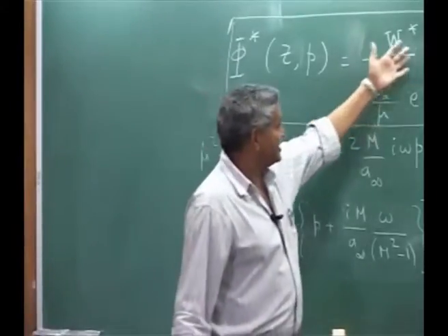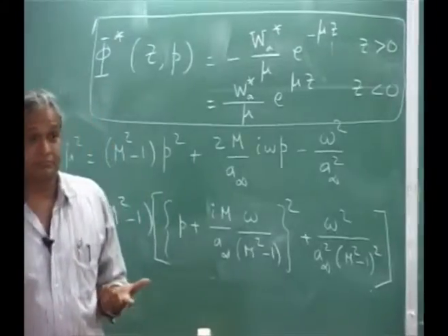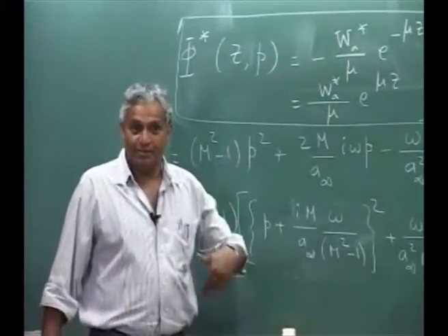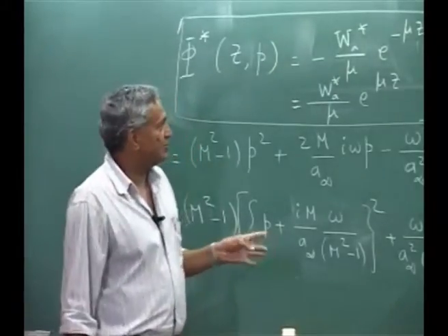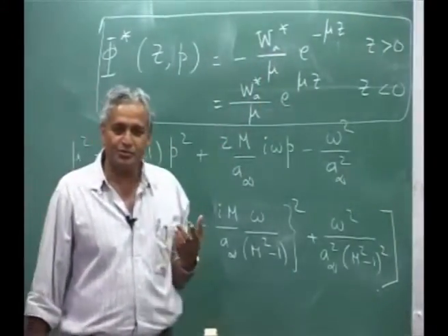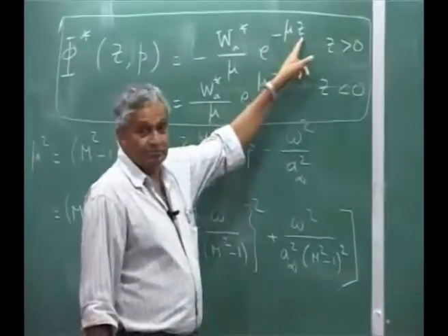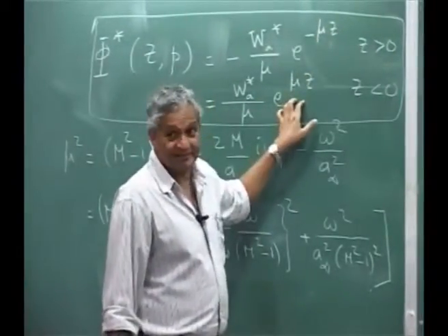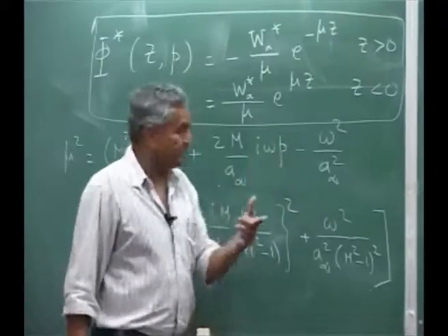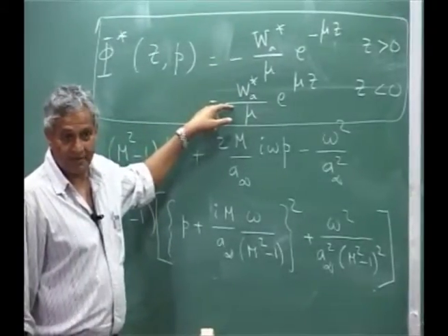Otherwise, you have to get this Laplace inverse of this entire term, knowing the WA. Okay, that's why this becomes messy stuff. What is done is, hey, I am not going to do this full term Laplace inverse. Since I am interested only in the z equal to 0 plane, where my aerofoil is also sitting, I will put z equal to 0. The moment I put z equal to 0, this is gone, this is gone. Then I am having only z plus, z minus, the phi. But you see the antisymmetry. Okay, that is why you get the lift.